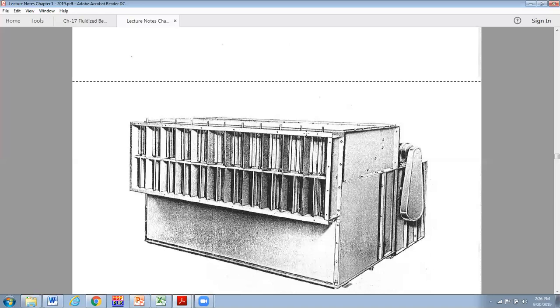A little space might just have a small duct that straps right on here that just covers up these first 2 dampers. On the other side, you might have a big auditorium. It might take up the other half of this thing with one duct. And then you could get cold air out of here and hot air out of here. And so you would just link all of those with mechanical linkages and have one actuator turning those posts all in unison to control the amount of hot and cold air that goes out to the space.